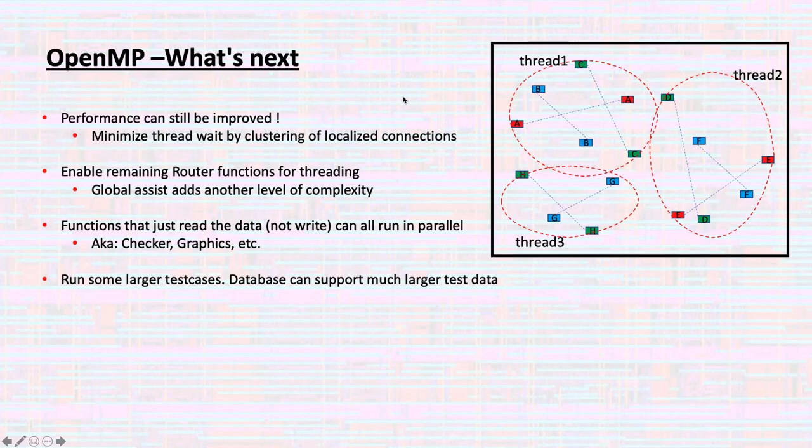In your 400K example, was this just routing or also strategies like rip up and retry? This is just routing, and the 15 minutes that I said to finish the 1,200 connections is the rip up and retry. Okay, so it will also rip up existing routes to get the missing 1,200 in. Absolutely, yes. And how much of that is parallelized? How much is running on OpenMP in parallel on multiple threads? Right now it's not. I haven't implemented that function yet.